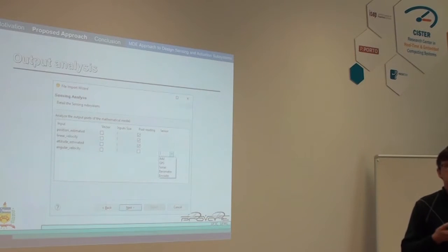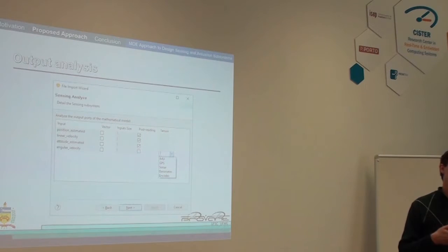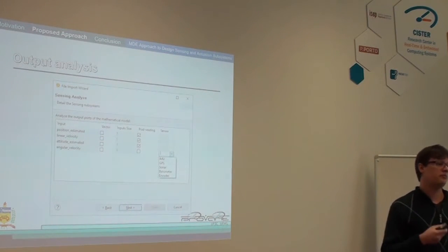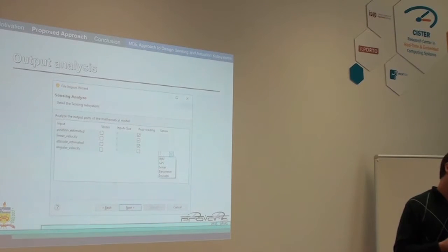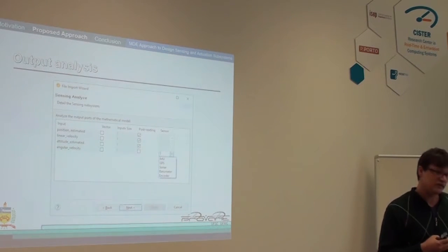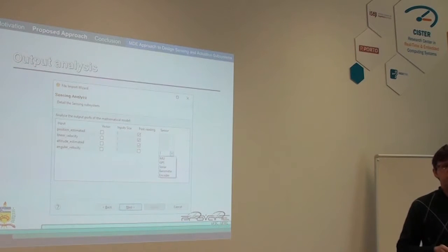We have one GPS that provides the position around every 10 milliseconds, and IMU and sonar sensors that provide the system behavior of the UAV around every 5 milliseconds. Because of that, we needed two different functions to process the data of these different sensors.